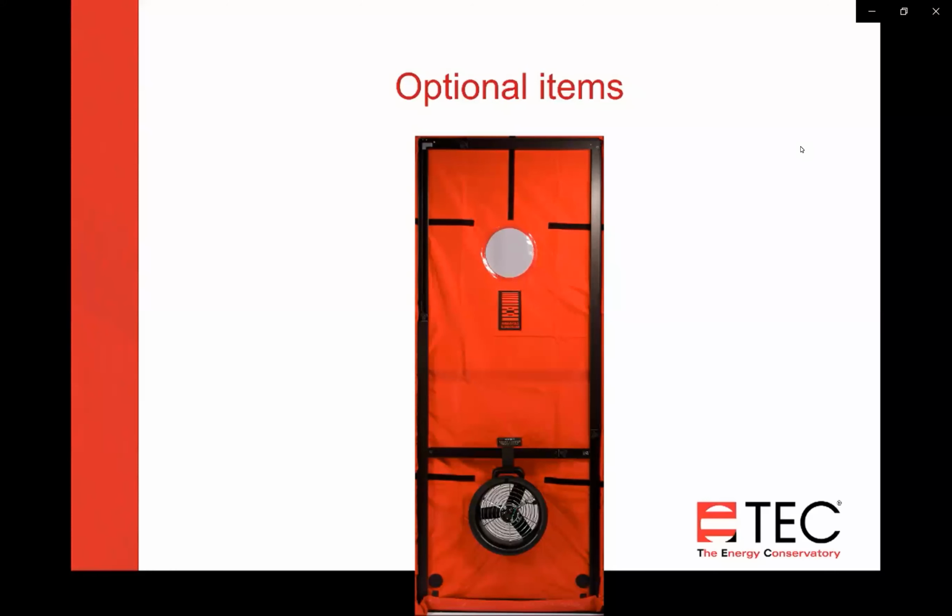So if you're doing code compliance at 3 air changes per hour, you can test small to medium sized homes up to about 3,000 square feet and get it up to 50 Pascal. That makes it a lot easier to do a blower door test if you can carry around the duct blaster fan, and in a lot of houses that would take care of it.